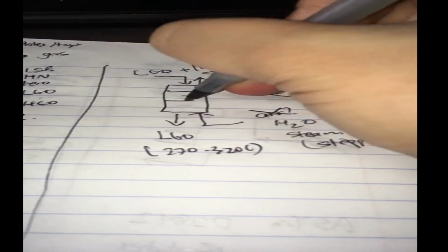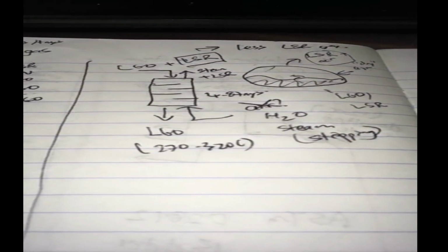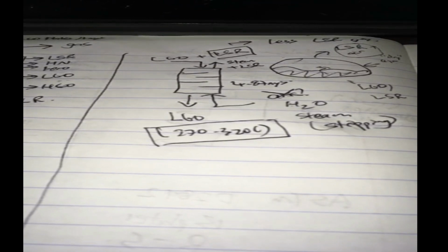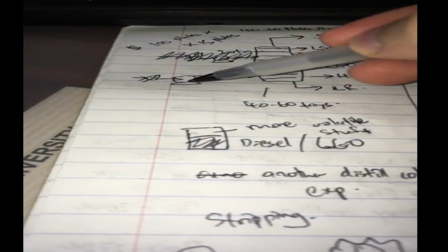And here you have about 4 to 8 trays. So this is what stripping does. Stripping gets the lighter stuff out of the mixture, and this is what you're left with. It's going to be much better, and the boiling range is going to be much more restricted. Now let's put this into our tower. I'm not going to draw the whole preheating and the heating and the pump again. So let's just draw this arrow to represent heated crude.